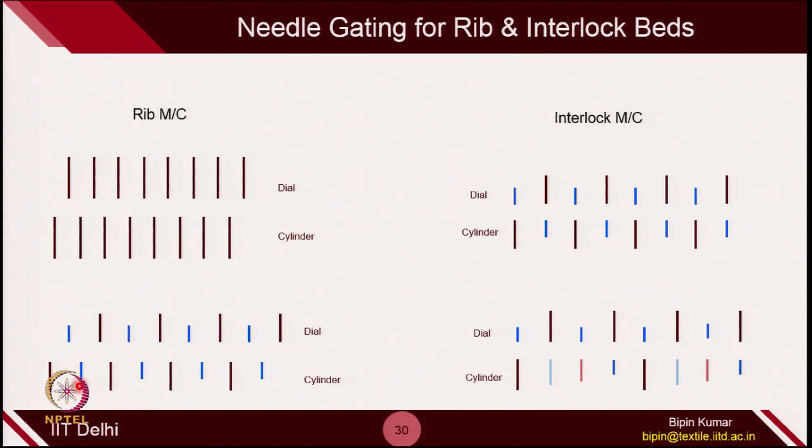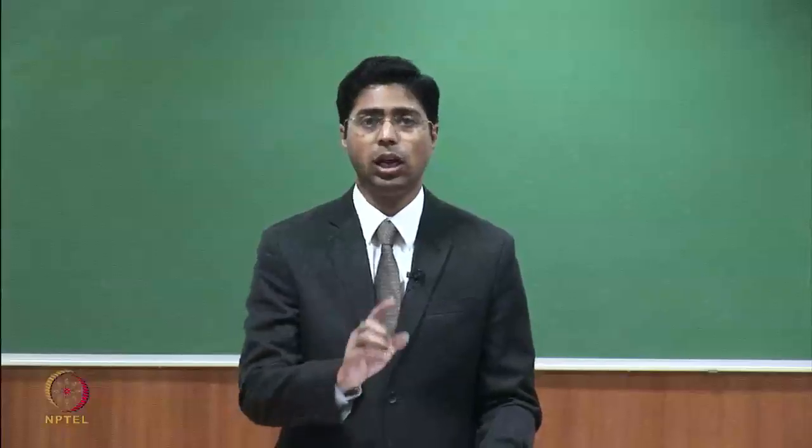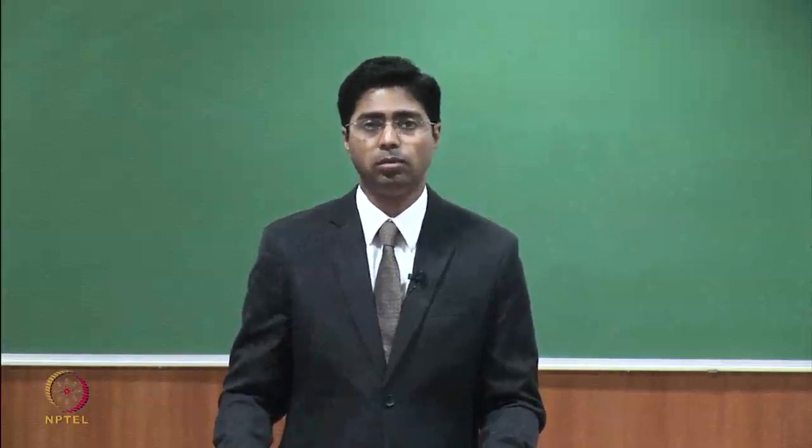So, sometimes you can select all the long butt needles of one bed, sometimes you can select all the short butt needles of one bed. This type of selection actually helps you in designing. So, once we start the designing next week, you will see how important the needle selection on a particular bed is, because this gives you a lot of flexibility in fabric design.